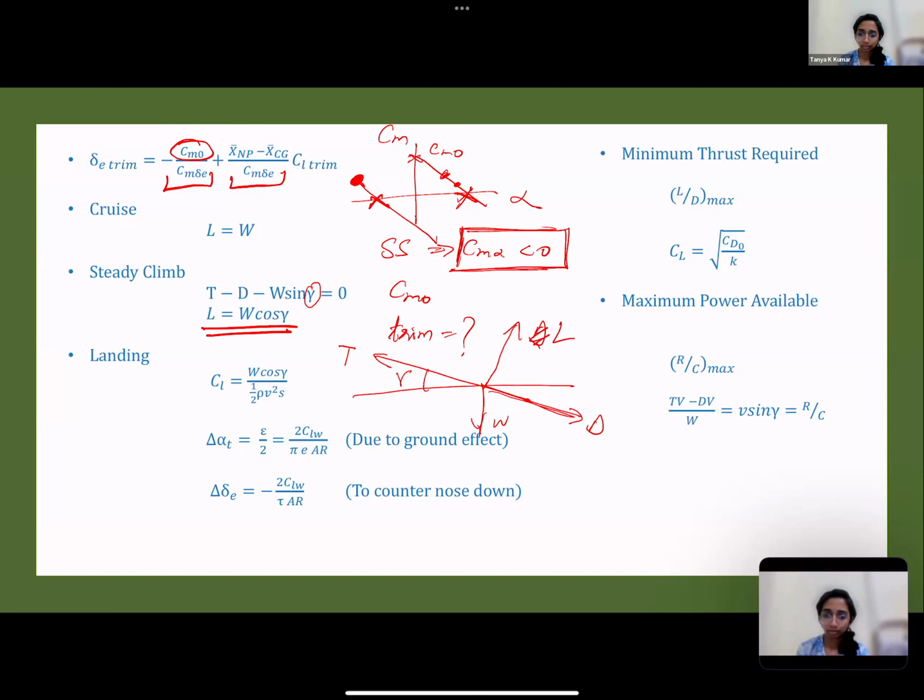Just guess. From the free body diagram, thrust is in this direction, so the aircraft is moving in that direction. Angle with respect to inclination. What is inclination? So it is the flight path angle. Gamma is the flight path angle or climb angle in this case. Inclination, I'm not sure, is a term that we have defined for aircraft. So it is the flight path angle, gamma.